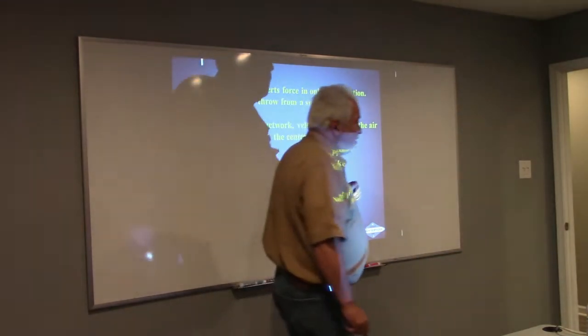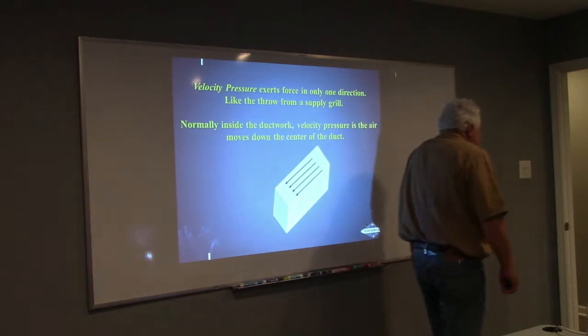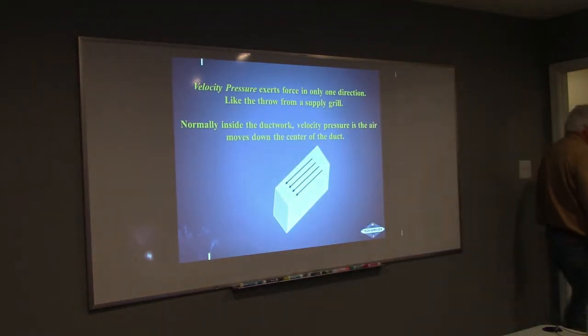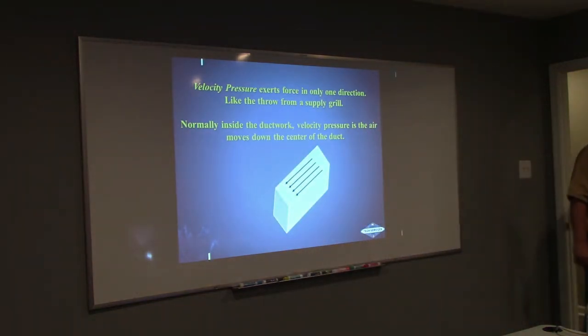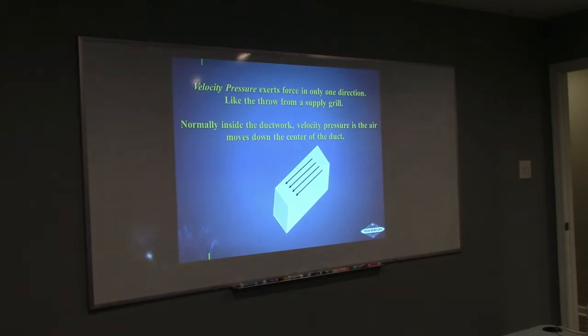And when you turn that duct, that velocity is going straight down there, and it says, oh, don't bother me, until it hits the turn. And then it starts hitting on the side. It starts rolling around. And then it bounces off to this side and comes back. What is that doing when I have all of that air hitting all of those walls? Slowing it down. It's resistance. So tell me, Hunter.